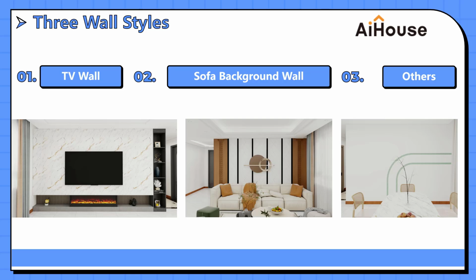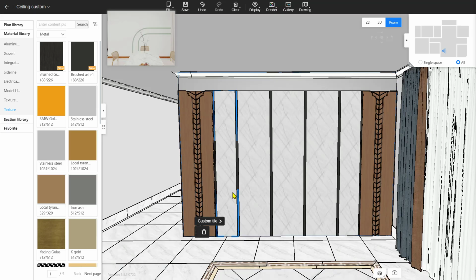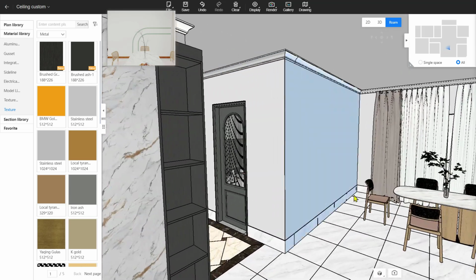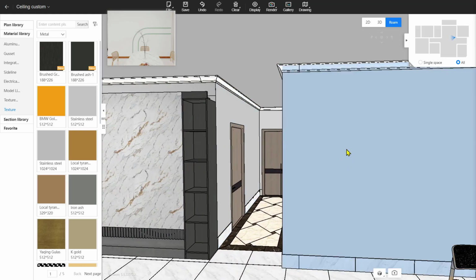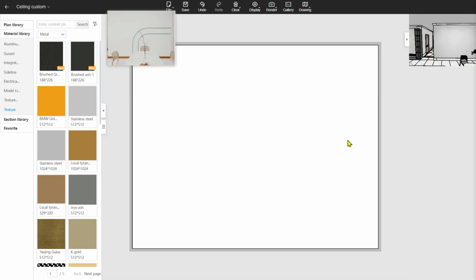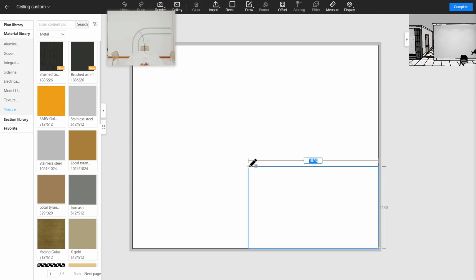I'm going to stick it on my screen also. Okay, now let's find this wall. I'm using this one to design it. So just double left click to get in. First we need to draw a rectangle for it, and start from here. You can set its distance, like 2000 and another one is 1200. Hit enter, and right click to end the command.